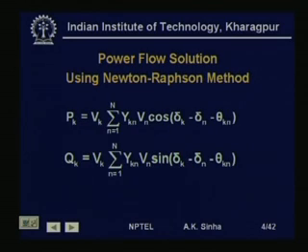We will start with the power flow equations that we had developed earlier, where we had said that a real power injection at any bus k is given by P_k, and P_k is equal to V_k summation n equal to 1 to capital N |y_kn| V_n cos(delta_k minus delta_n minus theta_kn), where V_k and V_n are the voltage magnitudes at bus k and n.